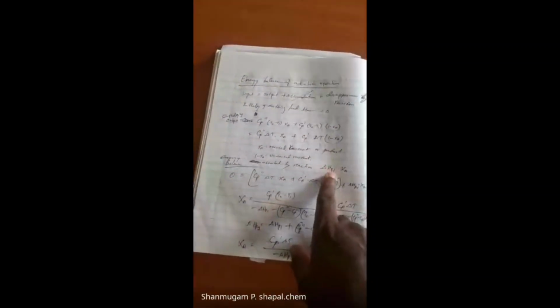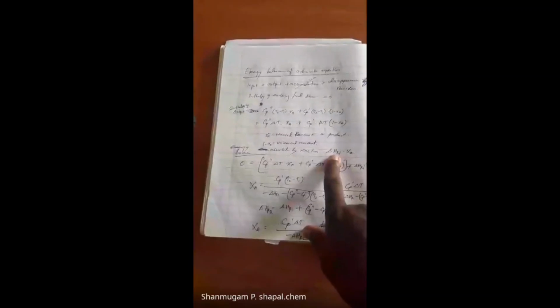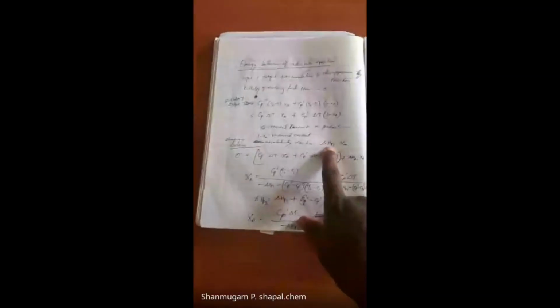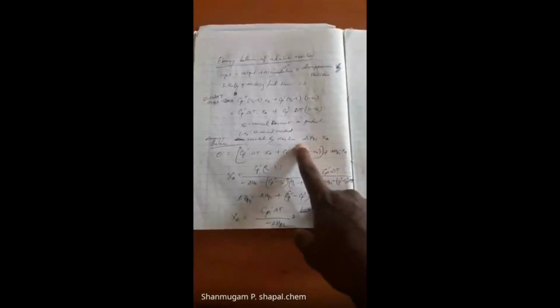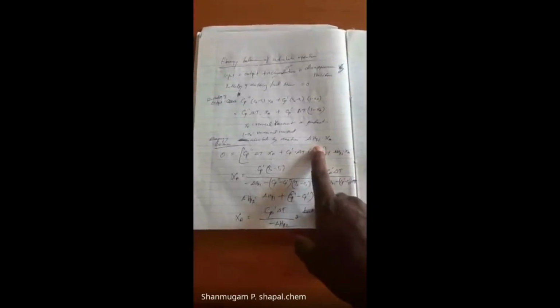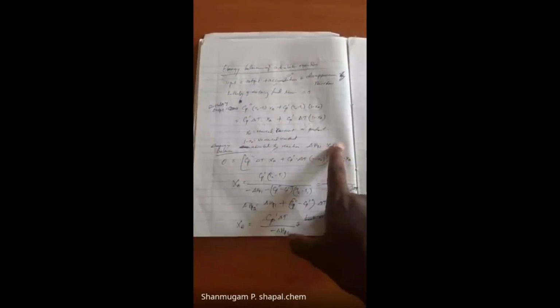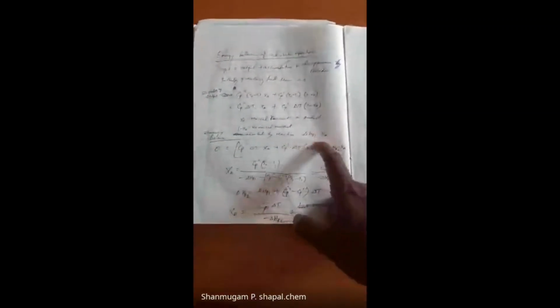And the next one is the reaction. The enthalpy or the energy that is absorbed, if it's absorbed, then we put plus delta HR. But if it's released, it's exothermic, then we put a minus delta HR here. So this is delta HR times XA. So how much conversion it takes, that much reaction heat is liberated here.